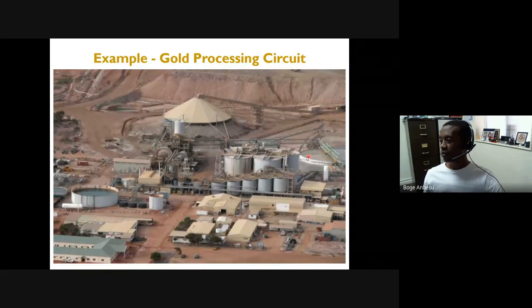So you tend to find large thickeners like this to recycle the water back. And also you need to do proper tailing management as well. So whatever you put to the tails needs to have a certain composition, a certain percent solid in them. So that is also managed through the use of thickeners and so on. Okay.